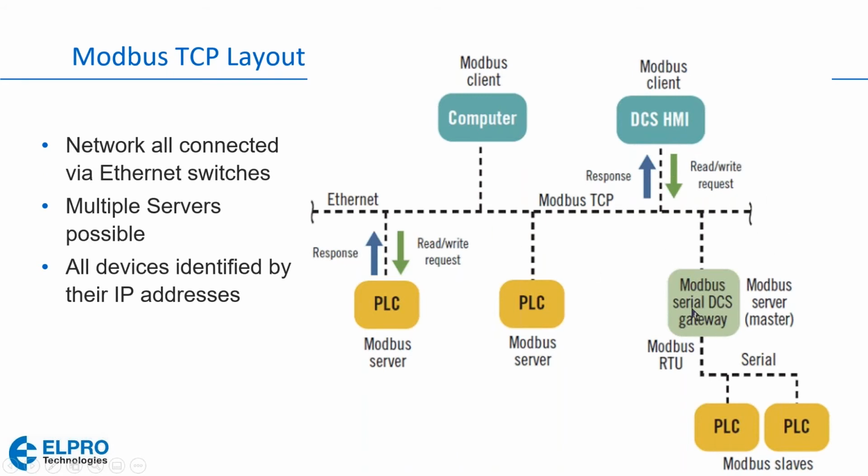And then down here, we have a Modbus TCP to RTU converter device. This is what all of our radios are capable of, as well as some of our other products, like our 945 and 245 Ethernet pass-through modems, as well as the 645 M-4 cellular modem. They can take a TCP message and convert it into Modbus RTU. So now you would have an RS-485 connection going to these older Modbus RTU devices. So we can combine Modbus TCP and Modbus RTU in the same network in this fashion.